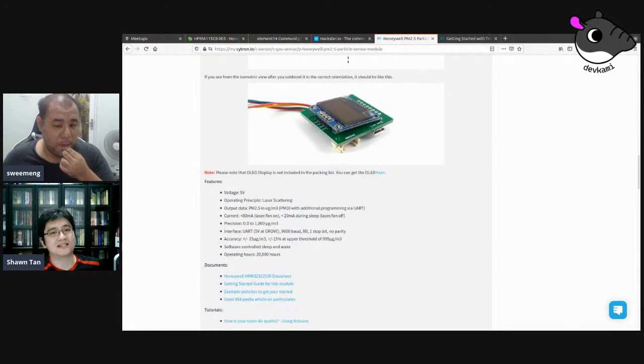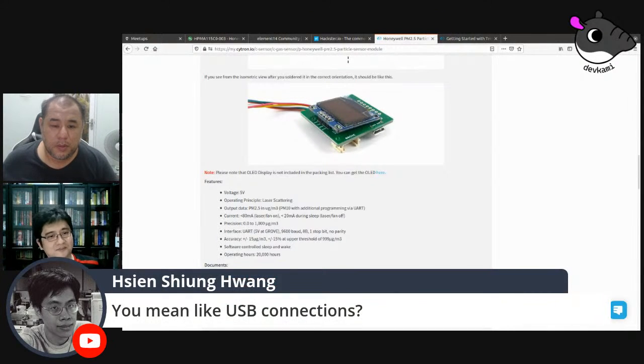If you're sending as an output, you can produce those frames so that on the other side, the receiver, if it's a real UART, thinks it's talking to a real UART because the frames coming in are valid frames. So that's the whole concept of Bitbanging, where you use software to twiddle the GPIO so that it behaves like some other device.